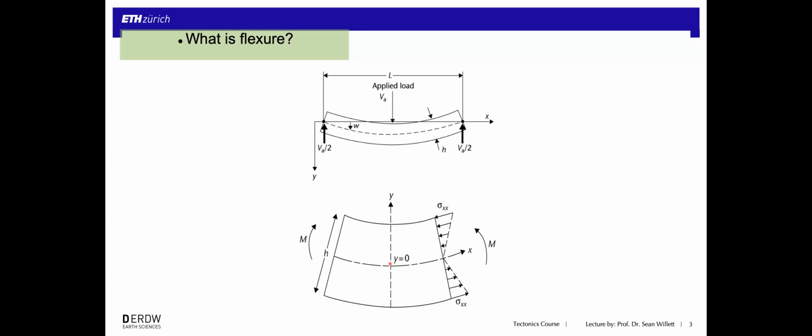There is no stress. And this sort of makes sense if you think about it, that if you bend a plate like this, the top part is going to be compressed because it's getting bent inward, and the bottom is going to be stretched out because it's getting pulled outward. And that's what this is. And what makes this a plate, or a thin plate, and defines this flexure then is that these, what we call fiber stresses, these horizontal stresses, are assumed to be the only thing that matters.